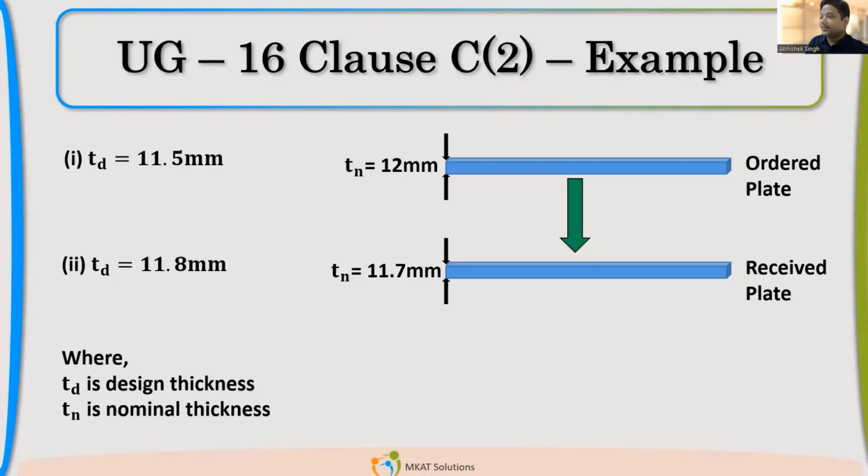Siva is saying yes. Umesh is saying yes. If you have not understood the question, I'll just repeat. My design thickness, which I got after adding corrosion allowance and everything, is 9.8. Can I order a 10 mm plate knowing that my under tolerance is 0.3? The supplier can give me a plate of 9.7 mm also. So I have most of the responses as no.